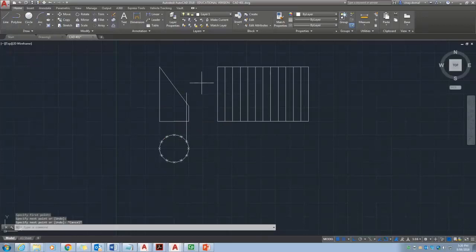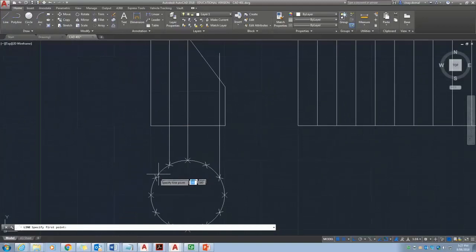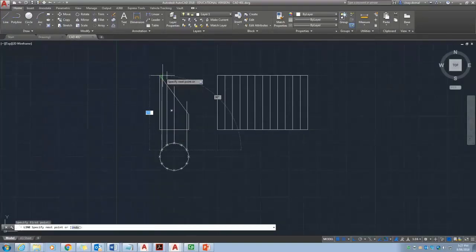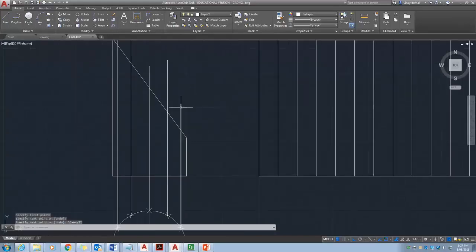Keep extending the lines from here, because object snaps will play around with you, but just be careful with that. I will also delimit the grid, so it's easy. Select the lines and snap it here. Once it is snapped, you can bring back this one to here.